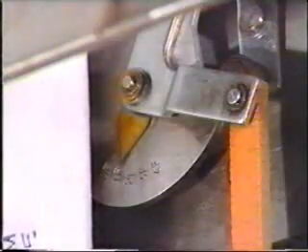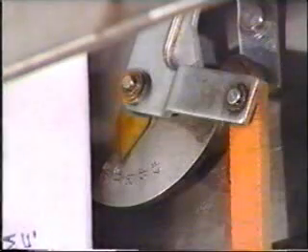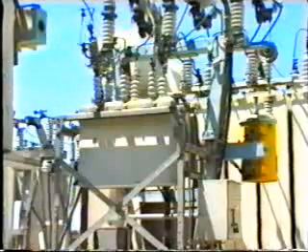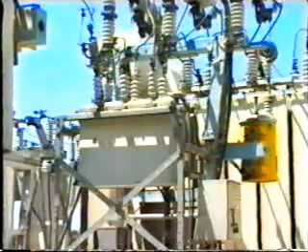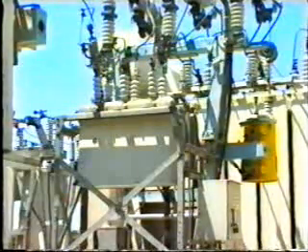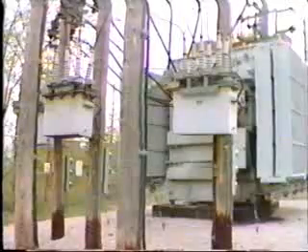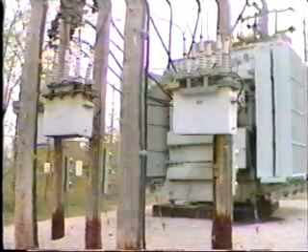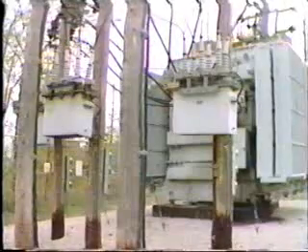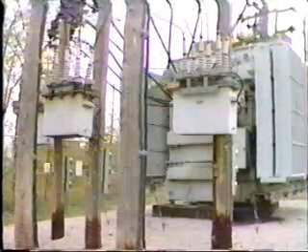The operation of the recloser is mechanical, and usually up to 4 attempts are provided with time delay settings between each attempt. Again, all of the settings need to be coordinated with other protection devices on the feeder, particularly the feeder breaker. Actually, the operation of reclosers on the distribution system does not really affect the stability of the power system very much. They are installed with the objective of reducing outage time to the customers.